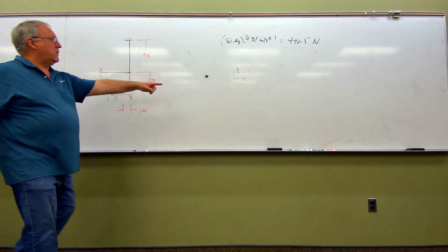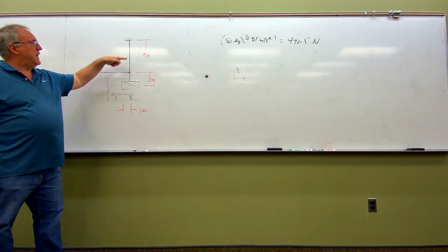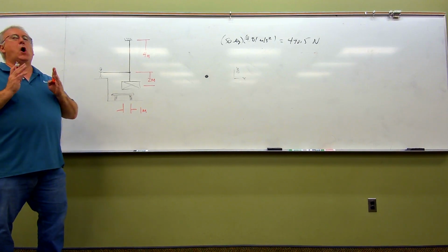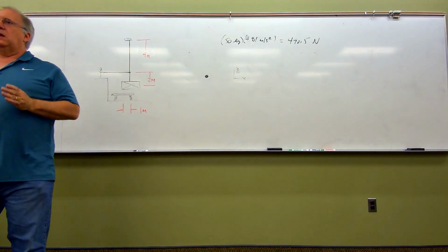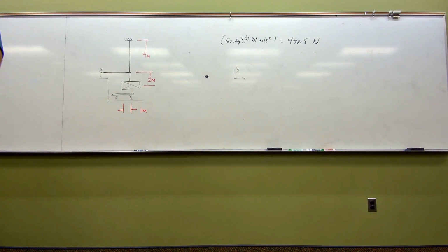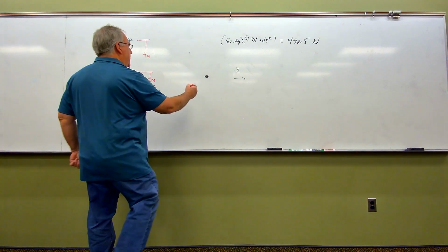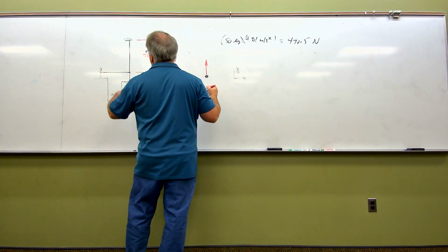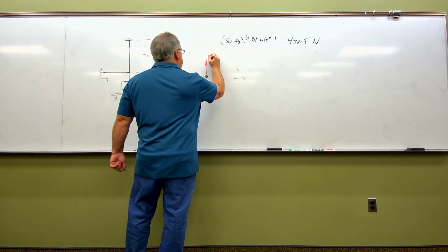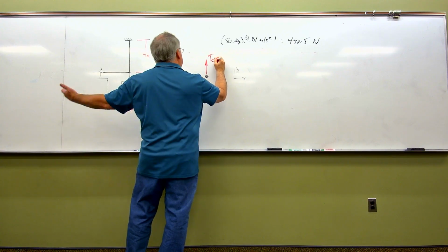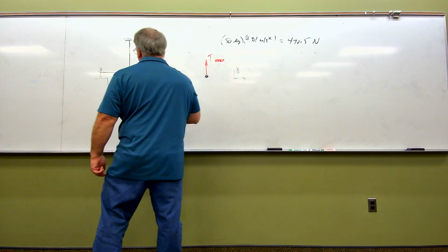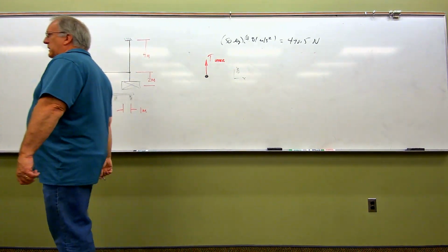So this knot right here used to be in contact with a cable right there, and we've already talked about this, from cables there are always tension forces. The line of action of the force goes along the line of action of the cable, and because it's a tension force, the arrow from the free body diagram must be drawn away from the knot. So I might have this here, and I'm going to call it T upper, meaning the upper cable. So the tension in the upper cable.